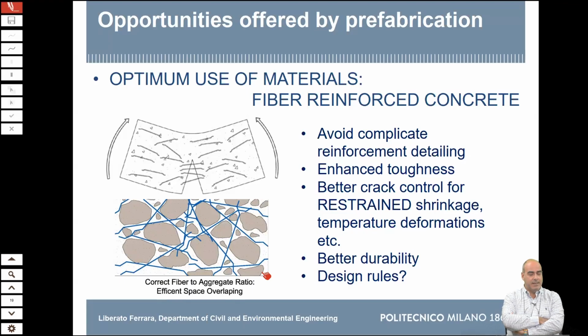widest produced precast elements in Italy and Europe: the elements for roofs, which can be in simple shapes like double T's, or can come in folded plates, shells, and so on. In that case, putting the transverse reinforcement into very thin elements, because one of the benefits is that you can have very thin elements, while putting in steel rods or some kind of shear reinforcement can sometimes be very complicated. So the companies were eager to replace those steel rods with fibers.